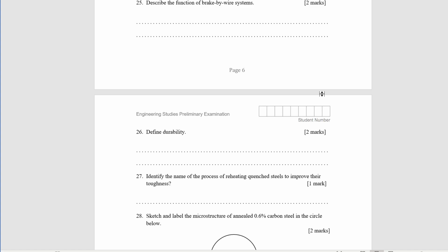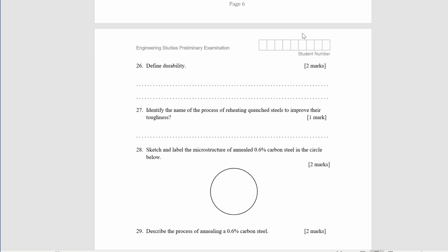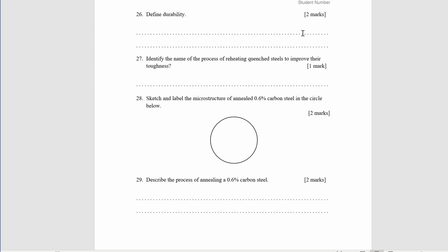If the question was explain, for an extra mark, what I would say is these have an advantage over traditional mechanical or hydraulic braking systems, in that they are more reliable and they have better response times and they have reduced weight. Weight's not as much of a problem when it comes to the Year 11 course. When we talk about fly-by-wire, weight becomes a big issue.